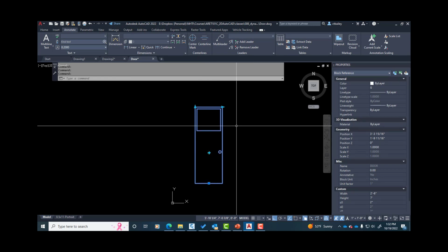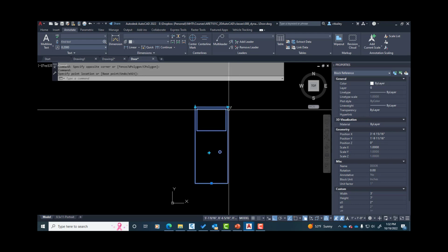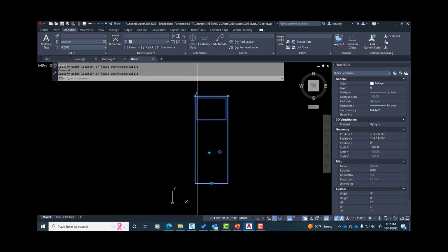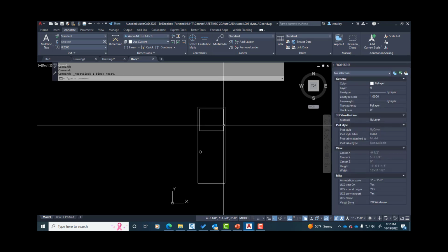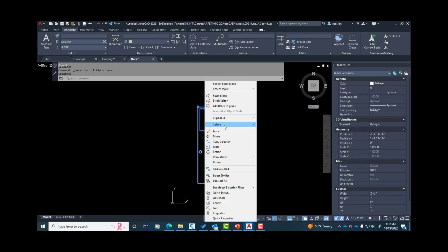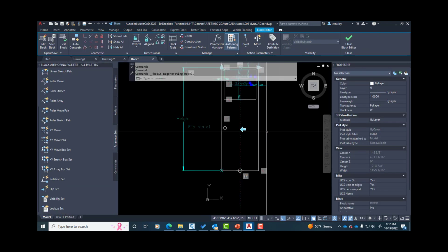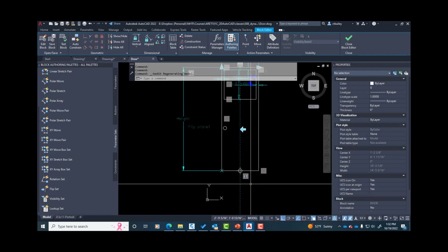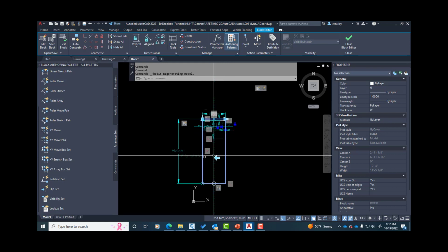Now, it's probably true that if I were to pull that, the doorknob will not move, okay? Because the doorknob didn't exist when we started that stretch. And it sure isn't going to move with respect to that because it didn't exist either. So let's go ahead and reset that block. Go back into the block editor. And we can add to the move. That's what we should do. We'll add the move. Where's our move? There it is up here.